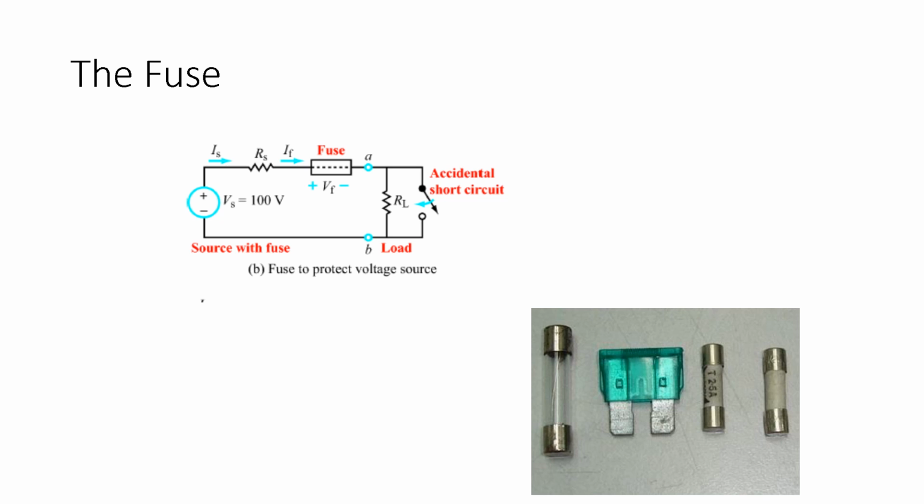As long as that load is sufficiently big, you're not going to burn out your power supply. However, let's short that circuit. So we have that little arrow there. Let's connect it. If we connect it, we see that absolutely none of the current is going to go through that RL.